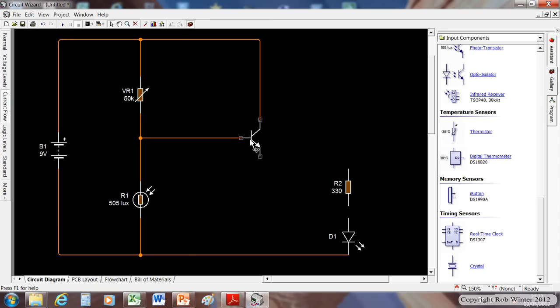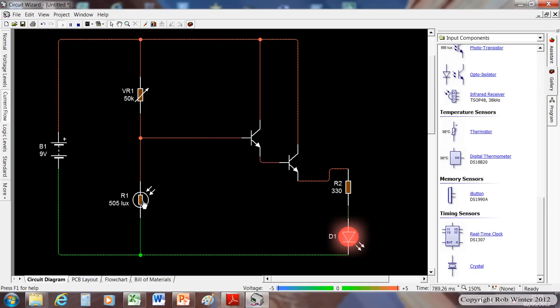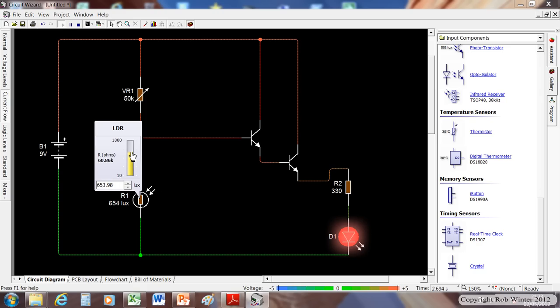Right? You have one transistor, I copy and paste, to make another, driving, rather than connecting to your output, you connect it to the base of another one, and then you connect the emitter of the second transistor to whatever you're trying to turn on. Both of these legs are collectors, so they can both collect energy from the battery. Okay. Now, you'll see this works in the same way, but what you might notice is it's very hard to get a fading LED now.